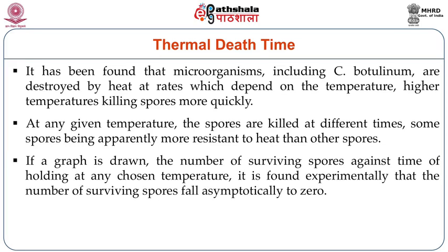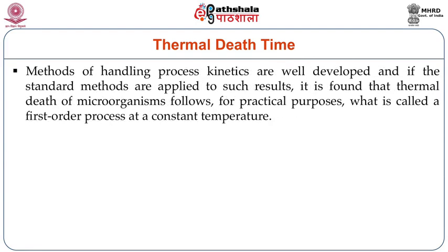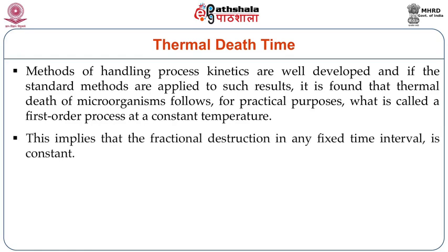If a graph is drawn of the number of surviving spores against the time of holding at any chosen temperature, it is found experimentally that the number of surviving spores falls asymptotically to zero. Methods of handling the process kinetics are very well developed, and if the standard methods are applied to such results, it is found that thermal death of microorganisms follows for practical purposes what is called a first order process at a constant temperature. This implies that fractional destruction in any fixed time interval is constant.